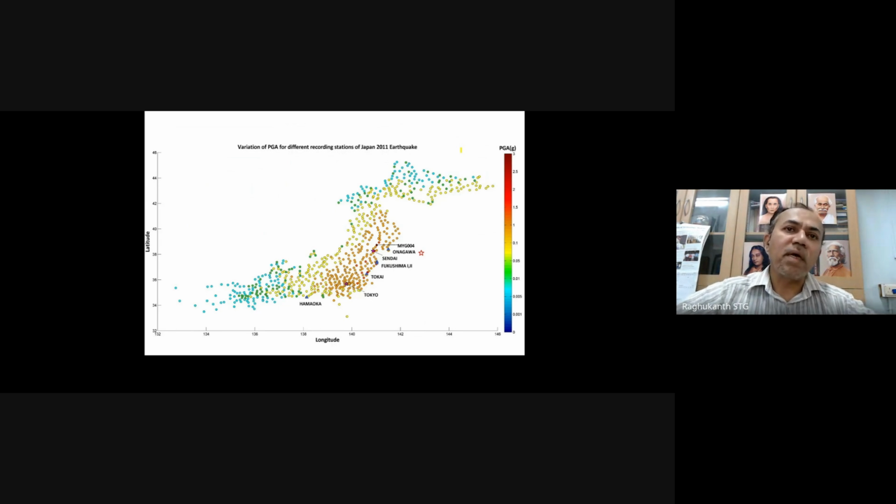Now when you look at the ground motions from recent earthquakes, many have been recorded. In the Japan 2011 earthquake, the maximum PGA at most of the stations was more than 3g, 2.5g, 2g. In our IS code the maximum value is 0.36g only. Of course, you can say that this earthquake had magnitude 9 and is very rare.